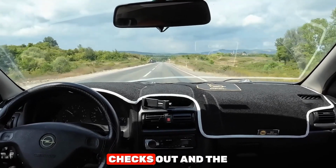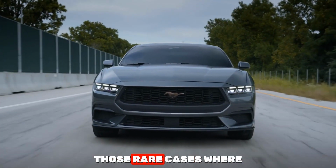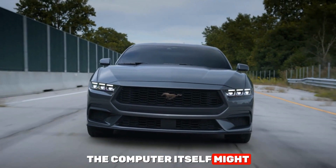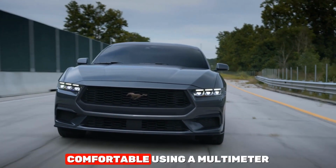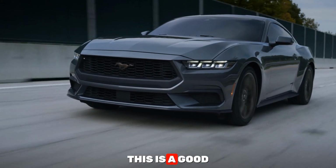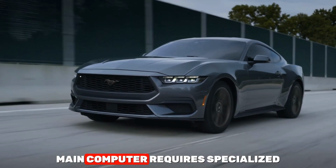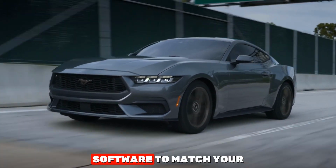If all the wiring checks out and the sensor is getting proper power and ground, this is one of those rare cases where the computer itself might be the problem. If you are not comfortable using a multimeter or reading wiring diagrams, this is a good time to take the vehicle to a professional shop, because replacing the main computer requires specialized software to match your specific vehicle identification number.